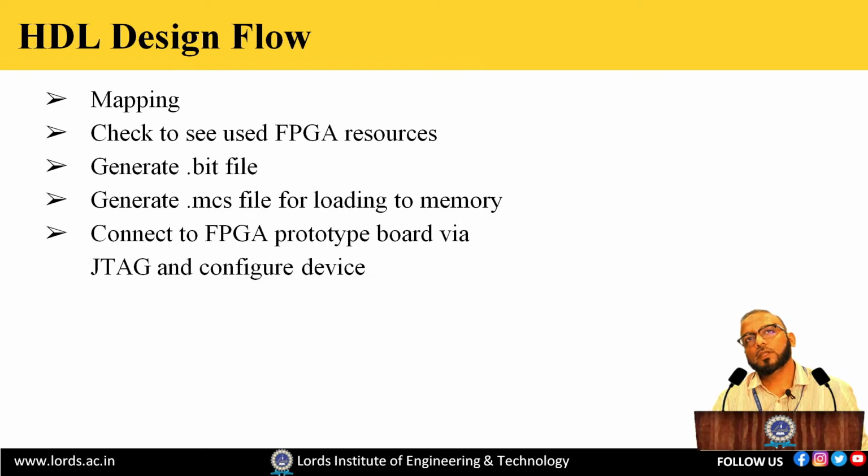After that, we have to connect to the FPGA prototype board via a JTAG cable and configure the device. The JTAG cable is the most common way of reconfiguring. If you look at embedded systems boards as well, we just connect through the JTAG or RS232 cable. There are many other options. Even system-on-chip boards are now so much easier that you can design and run Xilinx code on the same board and configure it.